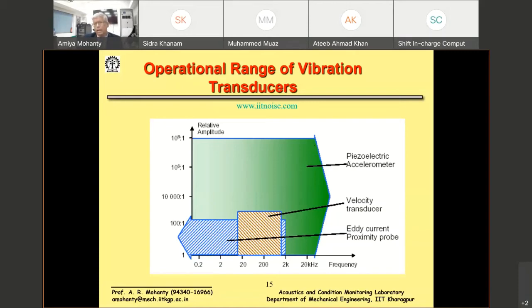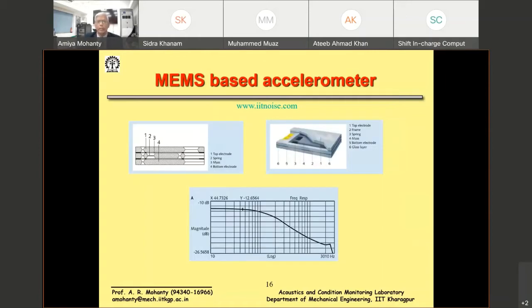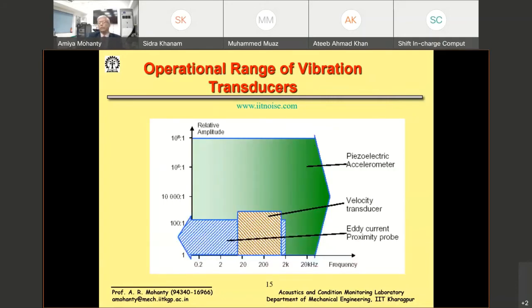So today the industry standard is that everybody measures vibration using contact type vibration transducers. Having said that, the problem is these piezoelectric accelerometers are very, very expensive, but many times we require to measure acceleration at very, very low frequency levels. For example, deployment of an airbag in your vehicle because you are rapidly decelerating because of an impending crash.